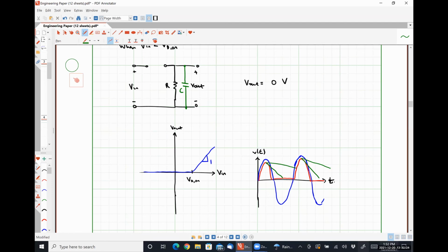Every single one of your laptop chargers has one of these. Actually, it has something slightly different. This is an example of what's called a half-wave rectifier because it's only rectifying the positive half of the wave. It's cutting off the negative half. Okay. We'll talk about a full-wave rectifier when we come back from the break, where a full-wave rectifier effectively flips the negative half cycle to positive so that we can use a smaller capacitor to get that DC output.